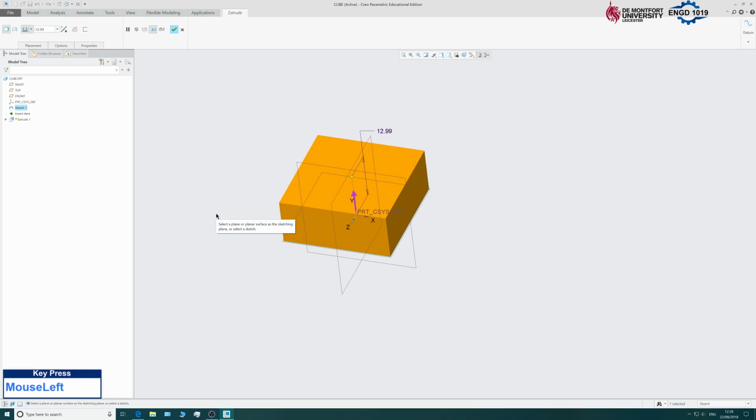And so at this point we can play around with this. There are various ways in which we can change the height. So we can click on this little ball with the left mouse button, hold, and we can drag it to wherever we want. We can double click here, add in a value, or if you come to the dialog box at the top, you'll see that it's changed to extrude, and we can enter a value in here. So 30.